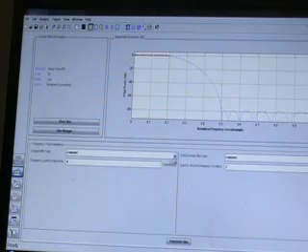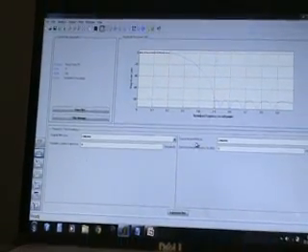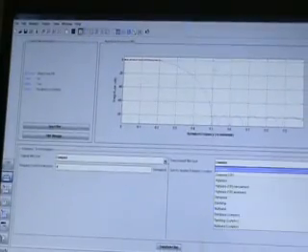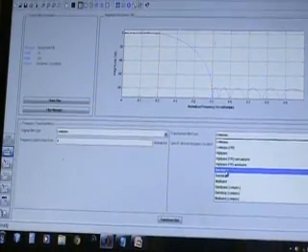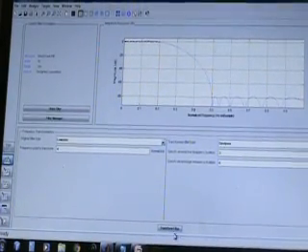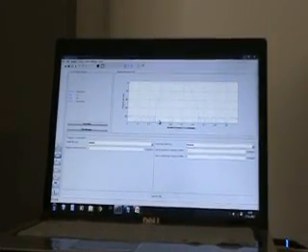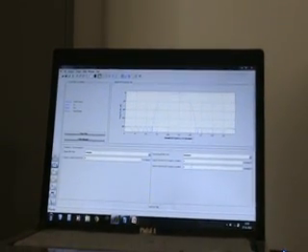As we have designed a low pass filter, we'll see with the low pass filter. And here the transform filter type is the filter type which we want to change. It can be anything. As we have designed a low pass filter, we'll select band pass filter and we click on transform filter. Then the low pass filter which we have designed is converted into band pass filter.